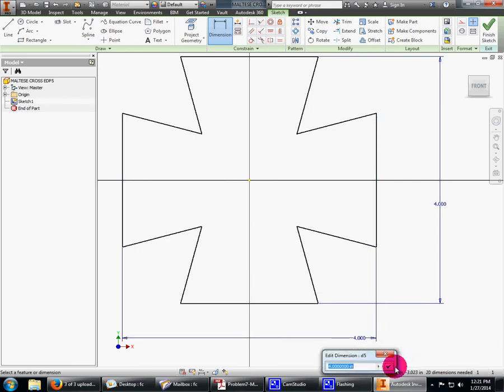And 4. And if you've done it right with that first constraint, see how it came to 4? That did because we told the sizes to match exactly. All right, so we've done that. Now we want to offset. And we want to offset at 0.125 on the inside.